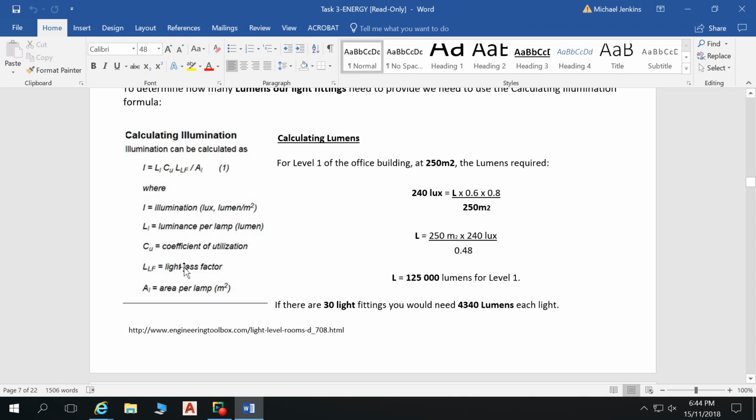So let's take a standard height of 2900 from the work surface, and then, actually no, it's going to be 2 meters from the work surface: a 2900 high ceiling, 900 high table, 2 meters, and we get a light loss factor as that light travels through the air. Those figures are going to be basically the same for whatever scenario you're doing a rough calculation of.